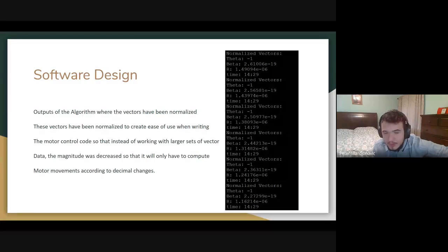Right. So our key component for our solar tracking system was the actual algorithm itself, and it just uses the basic current time function in C++ to compute accurate position data to find the sun with respect to the location of the solar panel using the current time. Basically, it calculates heliocentric longitude and latitude, stores them into arrays, and does a bunch of conversions so that we're able to find the actual position of the sun based off of the XYZ coordinates, or if we want, we can actually get spherical coordinates or polar coordinates as well.